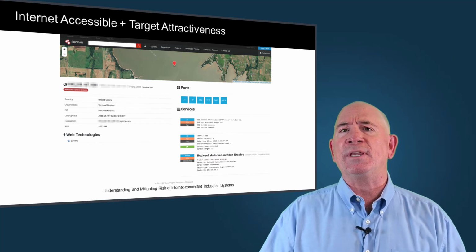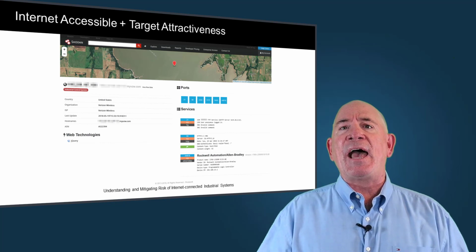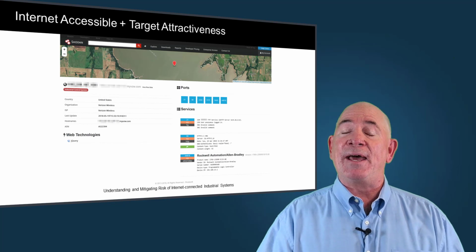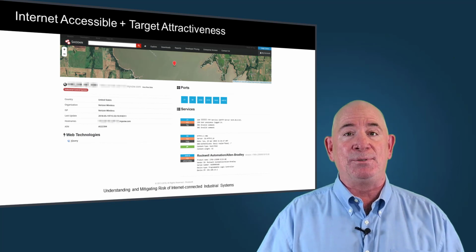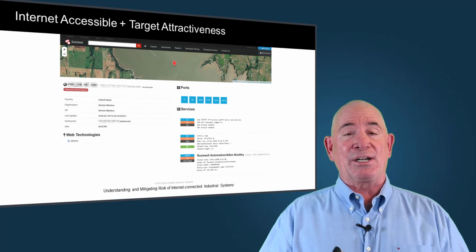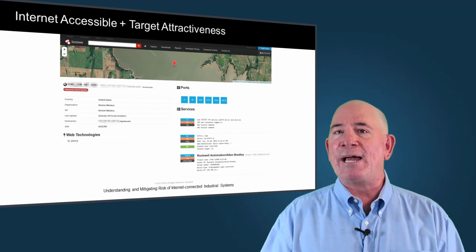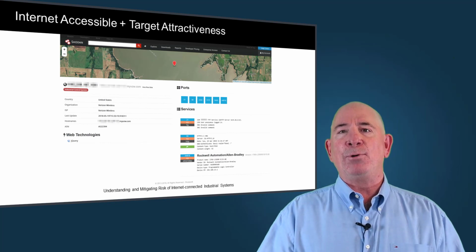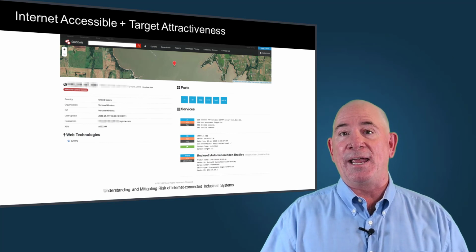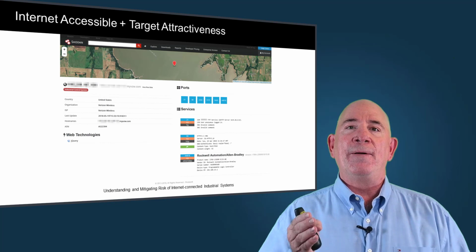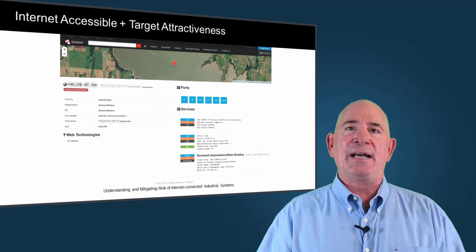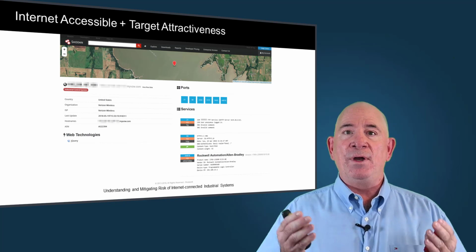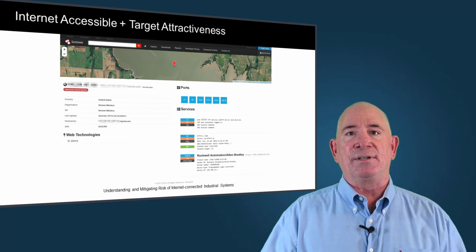A couple other important things to look at on this slide is the actual FTP banner. Since this was pre-configured by that OEM in their factory before it was ever shipped, they just simply put the client's name as the project name for this C-more panel, which automatically then put that name, the project name, as the FTP banner, fully disclosing the asset owner's attribution, their name in this case. So as you can imagine, this caused a lot of concern.